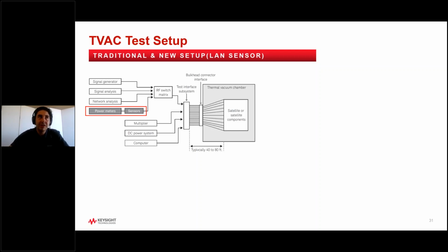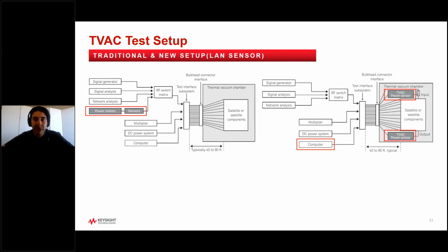As you can see here, with our devices under test being inside the thermal chamber and our reference plane for our device measurement being so far away, there are a lot of cable runs and areas in which we would really need to work quite aggressively to compensate for those uncertainties and areas in which the power that's being measured is not directly the power that's coming out of our DUT. So how can we take this one step further?